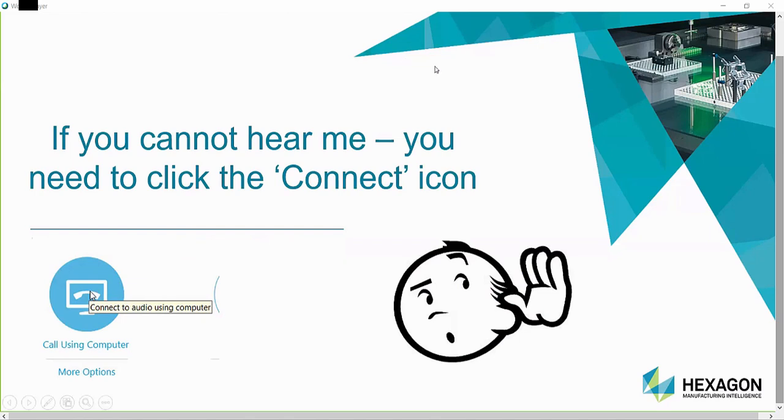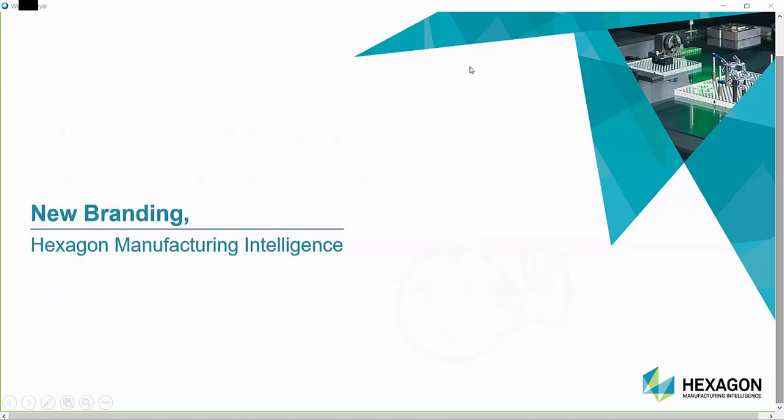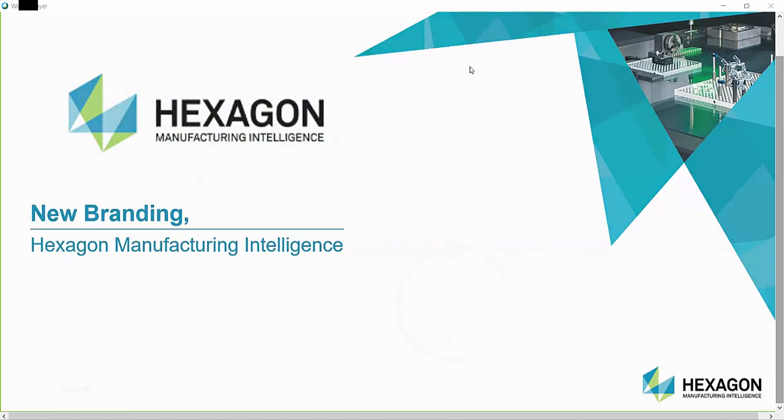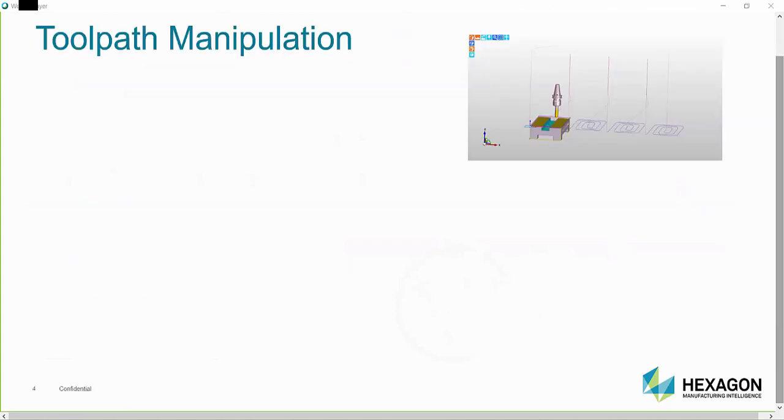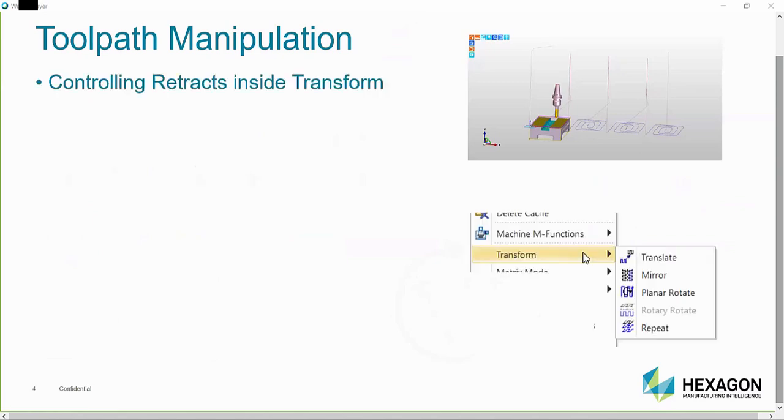Lots of nice ideas in today's presentation, and our first area is to talk about the physical toolpath inside Edgecam. As Edgecam users, we're used to using roughing, profiling, slotting, all the cycles, but we're going to talk about how to get extra control over there. One of the most important ones, and obviously a time-saving idea, is to use the transform, rotate, mirror commands. But people do talk about having some spurious moves when they use these commands. So David will show us how to remove those problems.